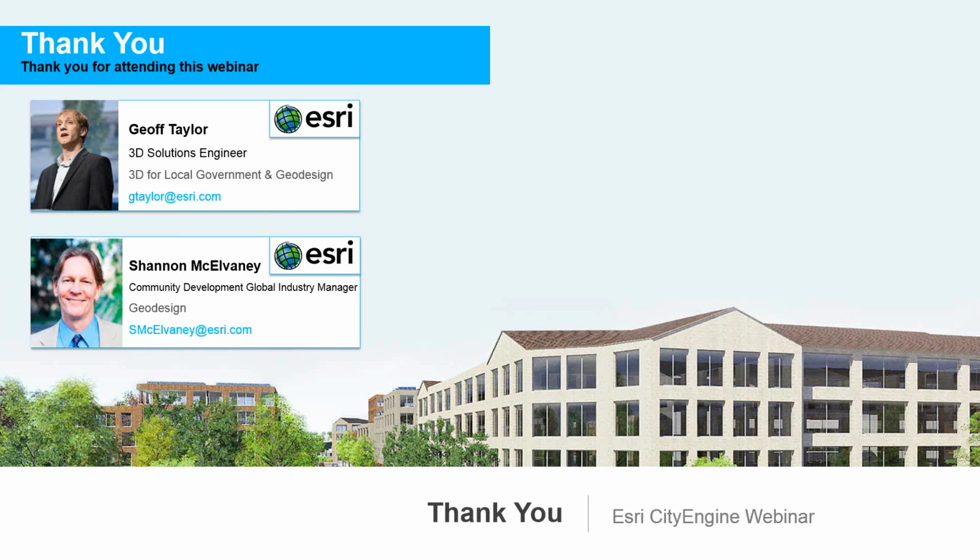There's a few approaches to doing this. What I would first recommend, and you can contact me directly, if anybody would like some of our most recent rules on creating existing conditions, just shoot me an email. I'll also send those out after this webinar within a certain time frame. You can leverage rules that you saw, for instance, for the city of Raleigh to create the existing conditions there and create their trees in 3D. But I also recommend downloading some of the newer rules for buildings that we've just released in CityEngine 2014, and they actually come with the package by default. You can use these to create your buildings in 3D.